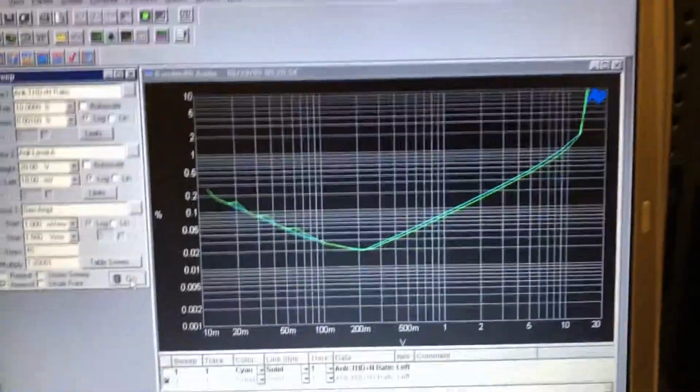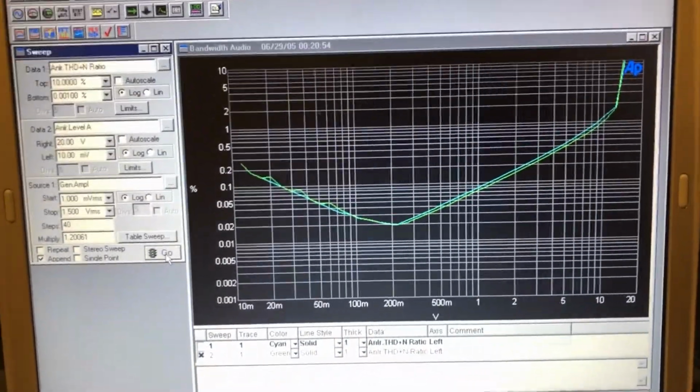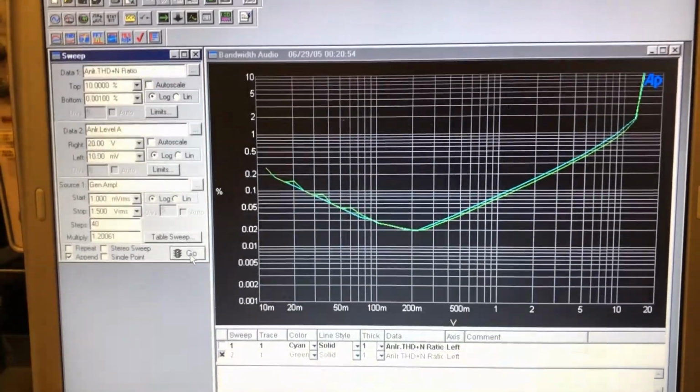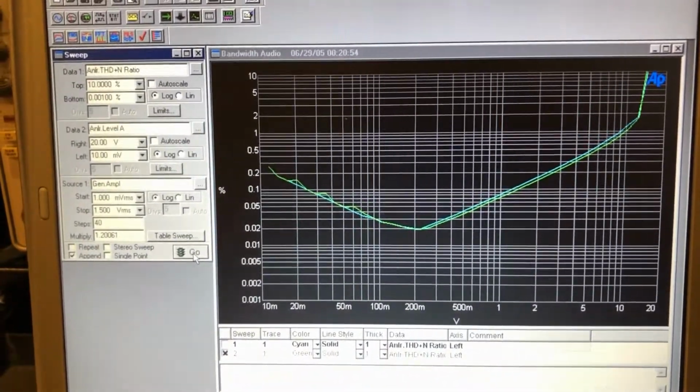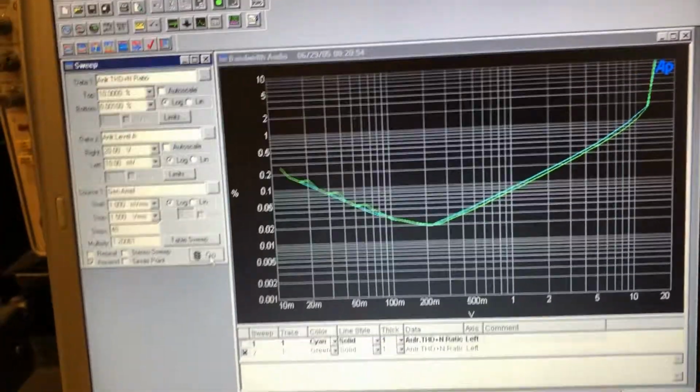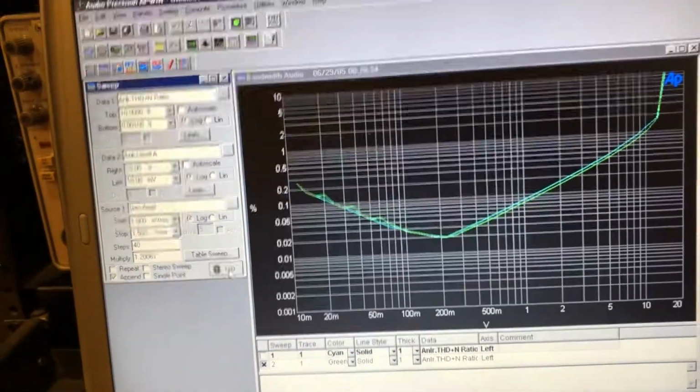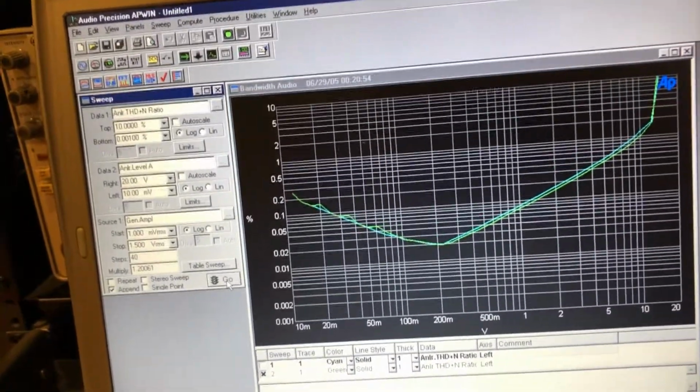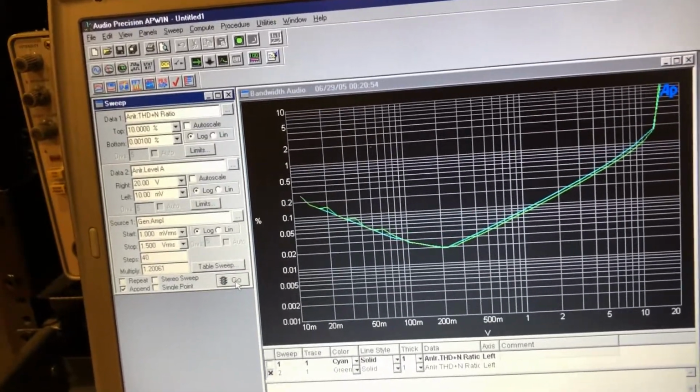I'll also caveat this now that this THD may not be representative. The AP is representing a pretty, as we've discussed before, capacitive load, and is capacitively loading the voltage divider too.